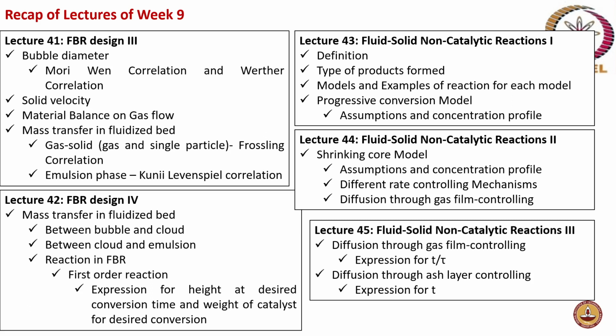And then the mass transfer in a fluidized bed reactor between the bubble and cloud, and then cloud and emulsion, and the reaction in a fluidized bed reactor, where the expression for a first order reaction, the expression for height at a desired conversion, time, and weight of catalyst for that desired conversion were discussed.